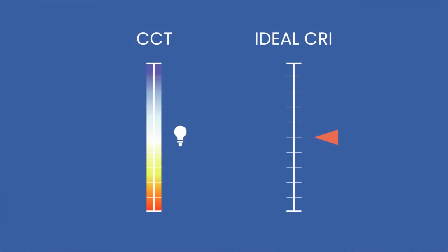The perception of color rendering, or CRI, is affected by the color temperature. The higher the color temperature, the greater the color rendering index value required by the observer to evaluate the environment as natural and comfortable. The lower the color temperature, the lower the color rendering value required to achieve this same feeling. Taking into account the fact that the IEC 60601-2-41 standard requires that surgical lamps offer a color temperature between 3000 and 6700 degrees Kelvin, what has been said therefore results in the partial irrelevance of color rendering.